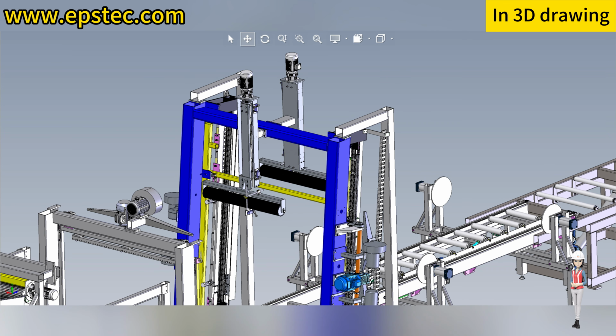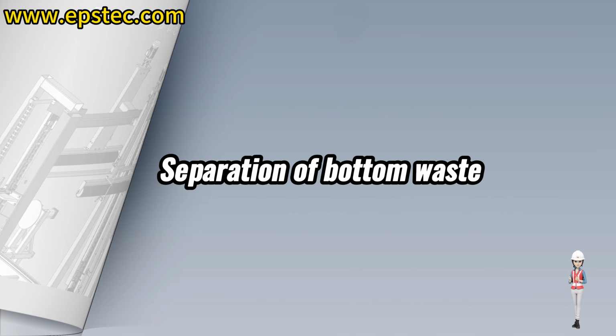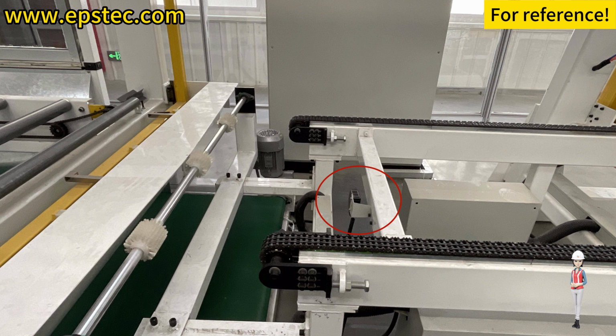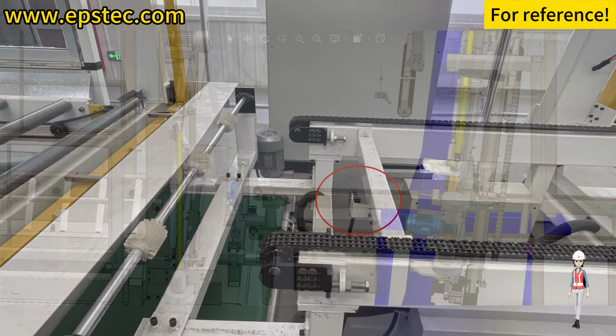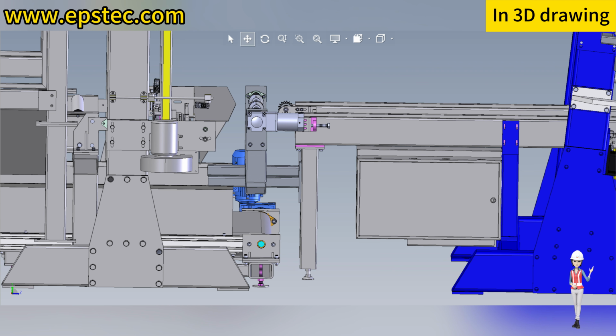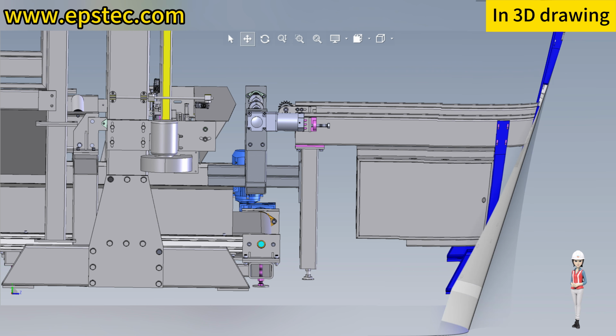Tip: the function of the front and back press-down rollers can be enabled or disabled. Separation of bottom waste. When the head of the EPS block reaches this photoelectric sensor, the brush starts rotation to separate the bottom waste, and the separated bottom waste falls into the bottom recycling system. It will convey the bottom waste forward all the way to the bottom crush machine.